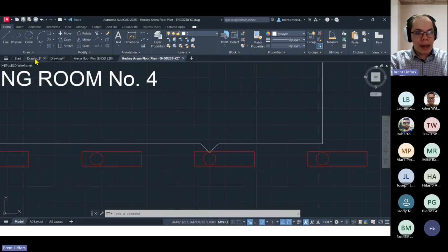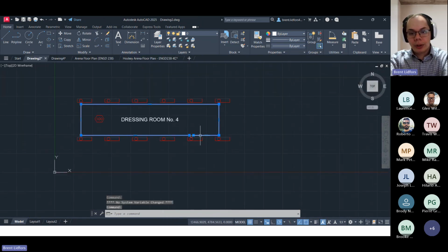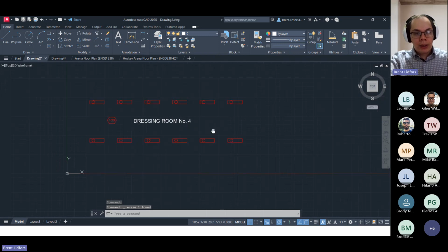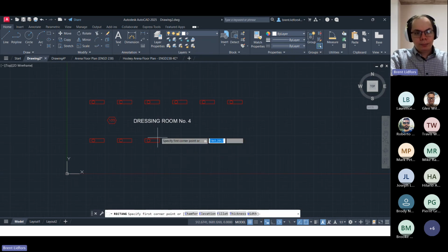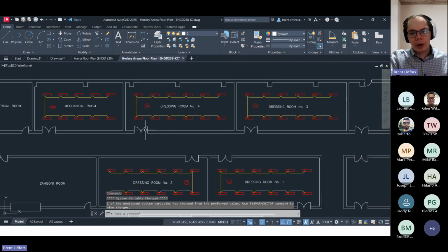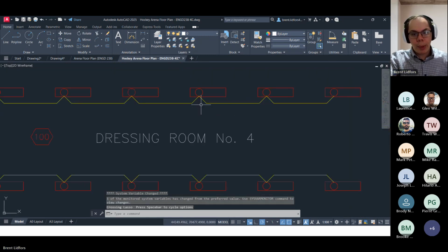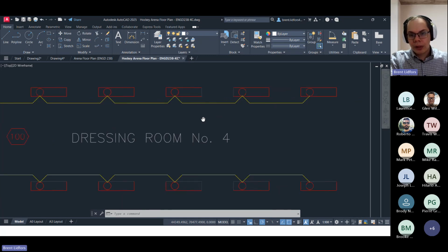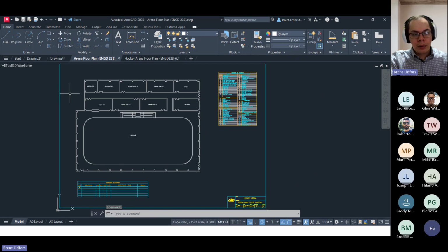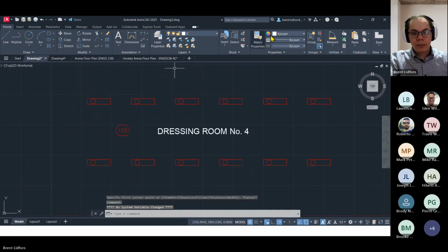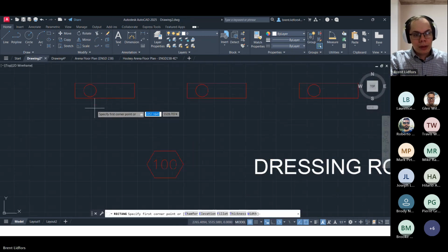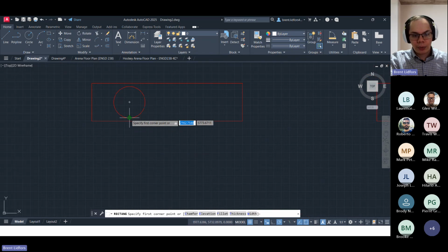Okay, so going back to how to make this a little simpler for the conduit. The easiest, probably most elegant way to do it, I'd think, is first of all, going back here to the conduit. The conduit itself is basically a rectangle, but there's little segments here where this little triangle shape or little arrow shape pokes out. So I'd start by going to the drawing and taking my rectangle and making sure this lines up exactly where it's supposed to connect.